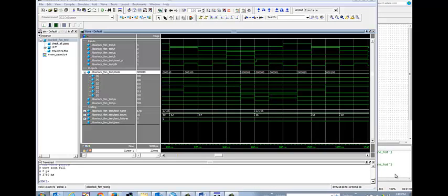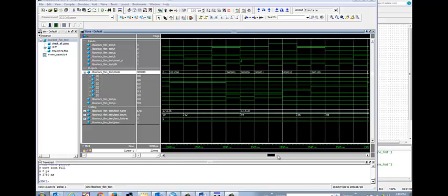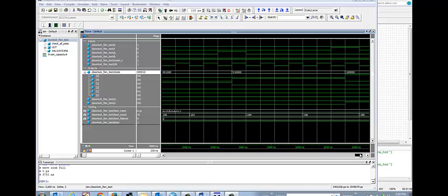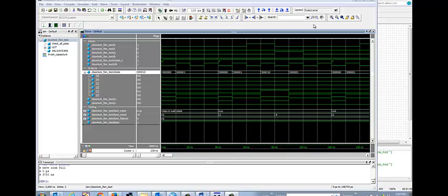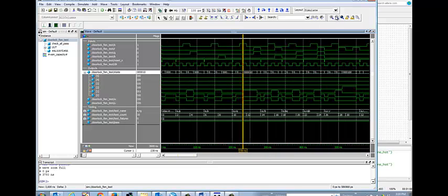Okay, so with ModelSim for the one hot encoding we have many of the same tests. Notice here we're checking all 6 of the flip-flops for our states, and we have each of the test names we can see here, SRG, SRAB, and so you can see there are lots of tests, basically 200 tests that I test for with this particular lab.